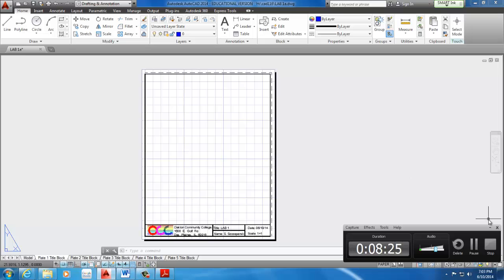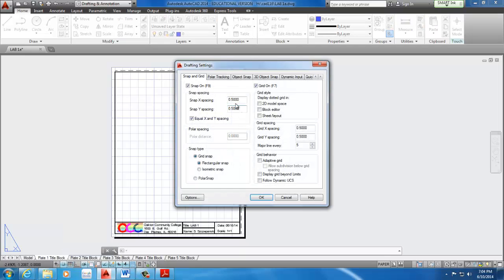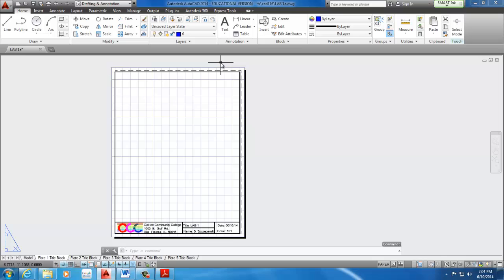So click left. So basically, once you have that on, the default settings, you don't have to worry about this. I'm going to show it to you guys. But if you want to adjust your grid, which we will in the future, but you don't have to do this, you right-click on it, and you get that setting options. There you can adjust the spacing on your grid and how it snaps. So here's your grid option, here's your snap option. These are the setups for both. It looks complicated? Kind of is. But actually it's pretty easy once you get a hang of it. So we'll leave that out for now. We'll get into that a little bit later in class. Or maybe next class. And we're going to start drawing.